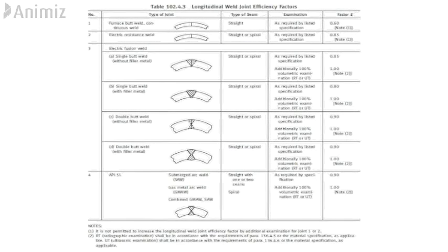So in my view, it is always safe to set the pressure of your safety relief devices less than MAWP by at least 10%. And if two devices are present, one should be set at 5% of MAWP, basically the safety valve, and the other, that is the secondary device, should be set at 10% of MAWP.